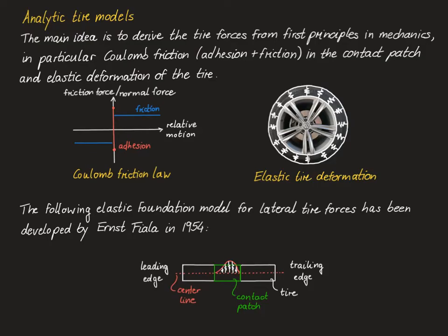The main idea of Fiala was to look at the deformation of the center line of the tire over the contact patch. So suppose this white rectangle represents the tire with the leading edge to the left and the trailing edge to the right, and in red we see the tire center line.